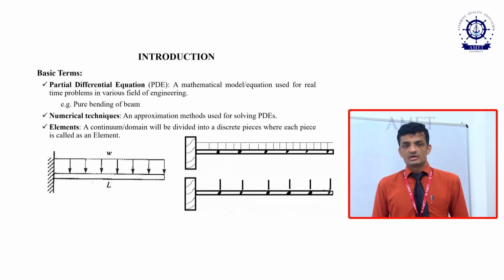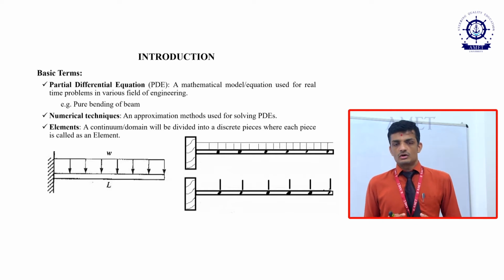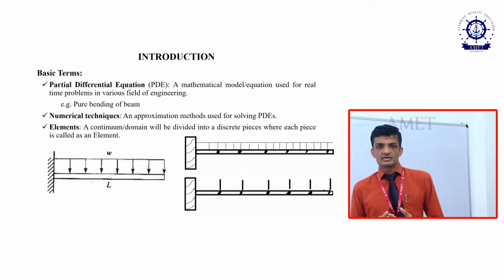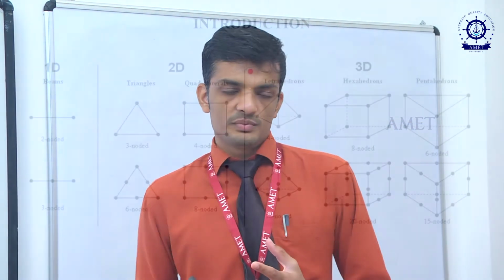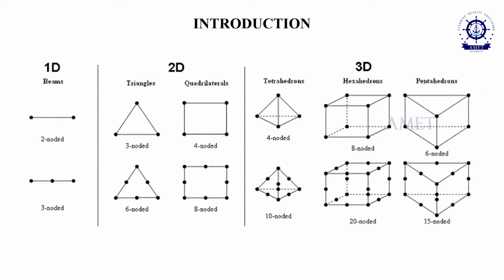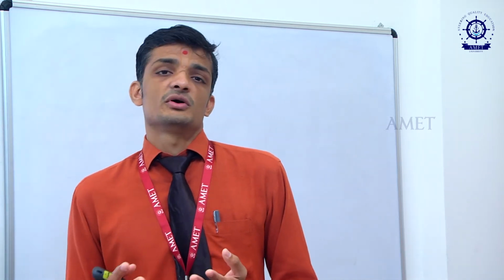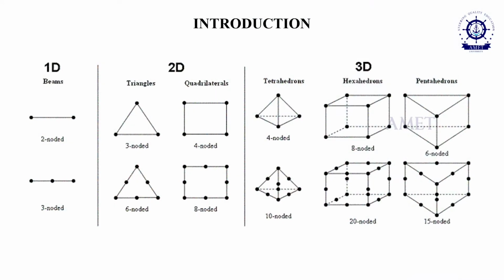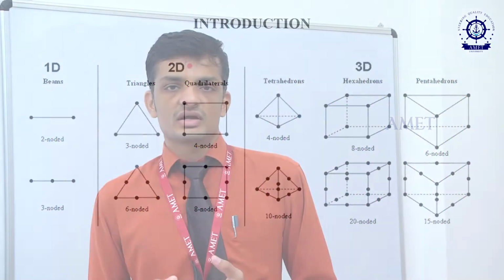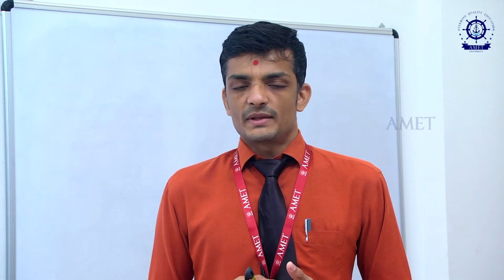It is problem specific. The same goes with any other problems like ship plates, or for example bulkheads, side shell, deck plate, and so on. As we know, the problem could be one dimensional, two dimensional, or three dimensional. In nature all problems are three dimensional, but under approximation they can be converted into 1D, 2D or 3D, and based on the problem you need to choose your element type. Normally for a 1D problem it is a line element, just a straight line. For 2D there are various geometries for 2D elements, for example rectangle, square, triangle, trapezium, and so on. For 3D, the 2D elements are called surface elements basically, and based on the problem you choose your element type. Again, it's problem specific.